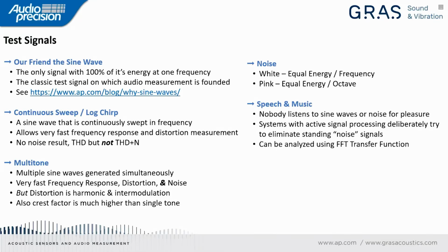Now, particularly in acoustics, noise itself is a very common test signal. And we don't just use any noise. I'd say the two most common are white noise, where we're looking at a signal which has a statistical distribution that gives us an equal amount of energy per frequency, or pink noise, which is an equal amount of energy per octave, which results in there being less energy as frequency goes up. I'll show, and we'll listen to each of those. One thing to keep in mind is pink noise to many people sounds more natural. If you just look at the spectrum of noise in, I'll say, the natural world, it has a very pink characteristic. There's more low frequency energy than high frequency energy in the world, acoustically.